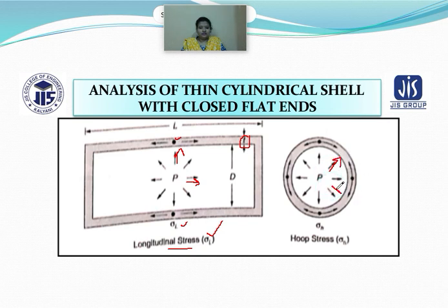This arrowhead is representing the pressure that has been exerted in the thickness of the inner wall of that particular cylinder, and you can see this point, this point and this point, whatever may be this point, these are all hoop stresses, and it is represented by sigma H. So from this pictorial view, hope it is clear how the longitudinal stress looks and how the hoop stresses look.